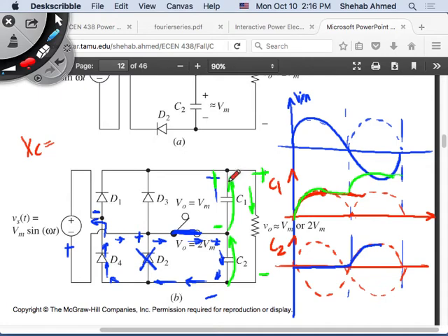Through the resistor, it will discharge through the resistor, but it has to have a full circuit. So the resistor is seeing this voltage. This is a closed loop. This is a closed circuit for the resistor, right? So the current through the resistor will equal the voltage across the two capacitors divided by the value of the resistor.